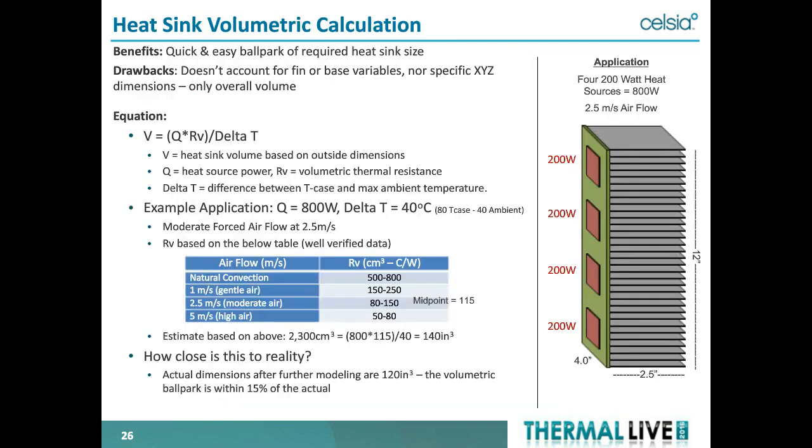Step one is always to do what we call a volumetric calculation. So you're sitting in a meeting where they're talking about the next product that you're going to work on, how much power you're going to have to take care of, and how little space they're going to give you to do that. The volumetric calculation allows you to get pretty close to a size that's required to do your cooling, based simply on a couple of numbers that you'll have early on in the design phase.